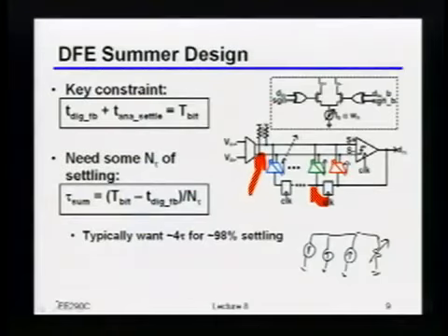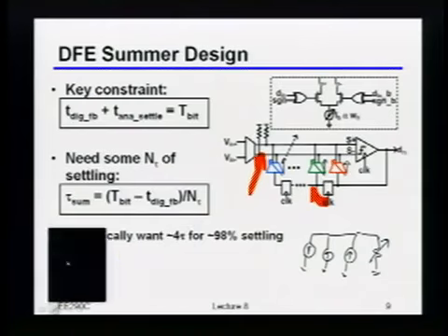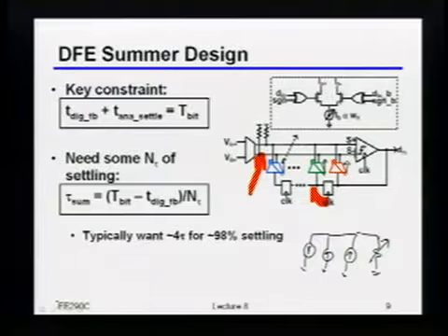Well, this bandwidth is just set by this resistance, right? So basically, the bandwidth on this node is exactly this number that I'm quoting here. You are right, by the way, that there may indeed be another preamp inside of the comparator, which would then mean that that also has an implication on how fast this can settle. But the good news is that it's fairly straightforward to figure out what the impact is. You can include that as a digital delay if you like. Does that make sense?